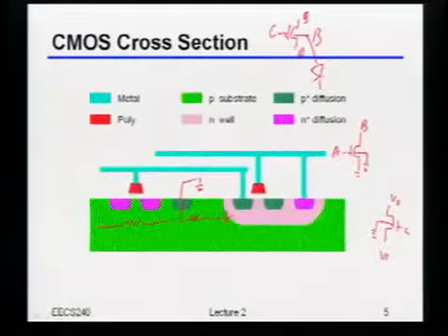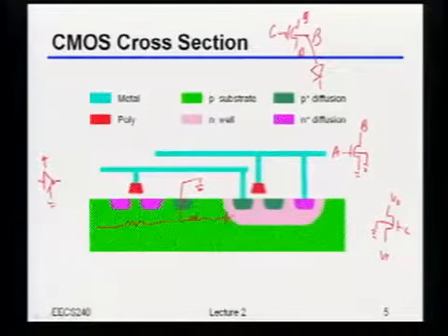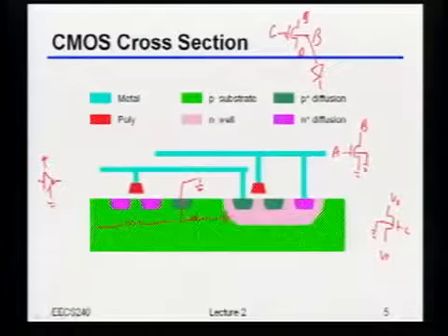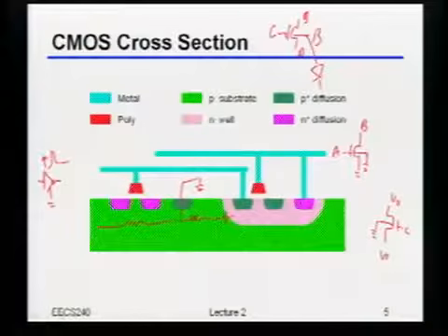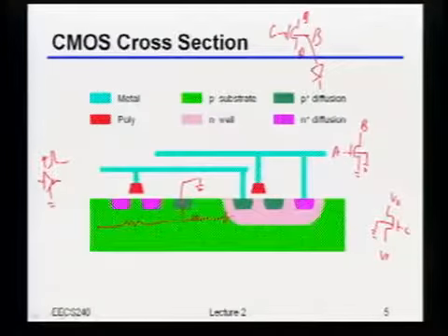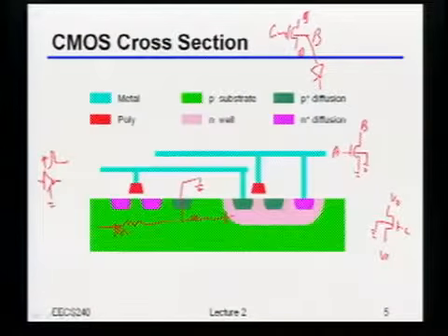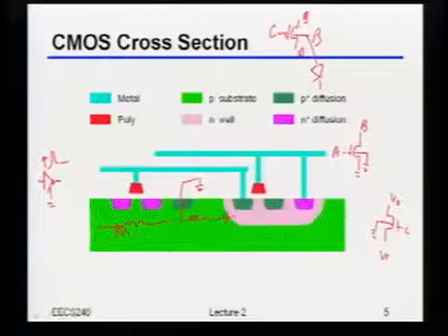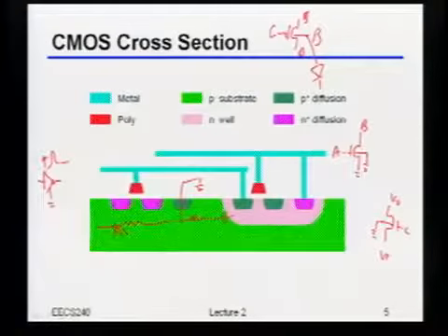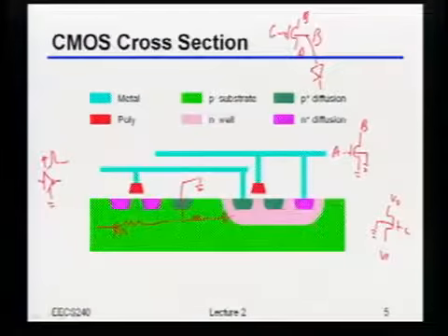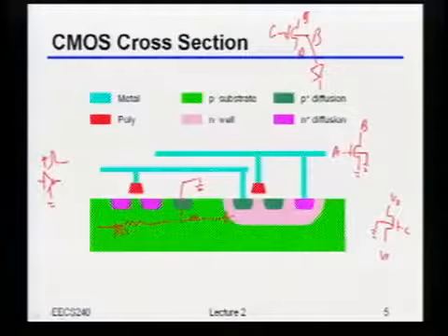In particular, you can imagine, let's say I have some digital circuit over here that's sitting right next to your analog circuit, right? That digital circuit, it's got really spiky current waveforms, right? Well, those little spiky current waveforms usually translate into some sort of variations on the voltage. And again, if you have some really sensitive analog circuit, that could basically screw up things that you care about. Okay? So again, this is not actually a point we're going to spend a lot of time on for a while, but just keep in mind, it's usually the stuff that you didn't think about that can come up and bite you at some point. Okay?